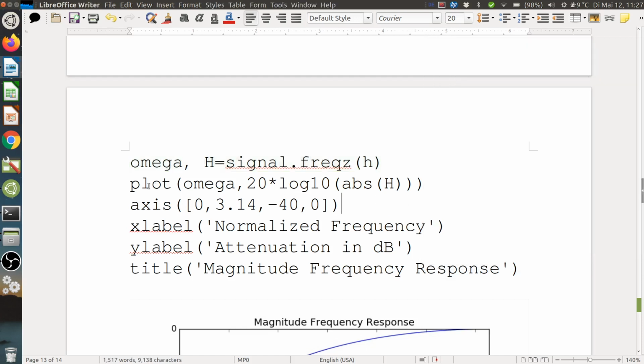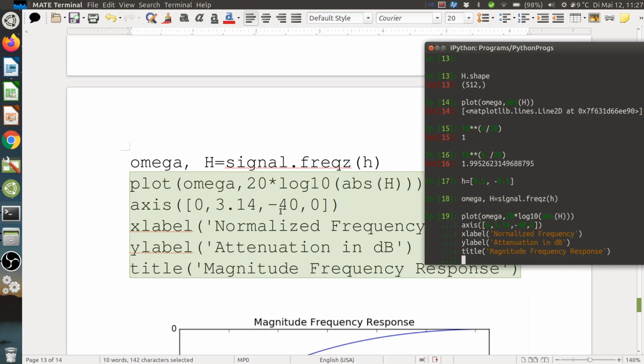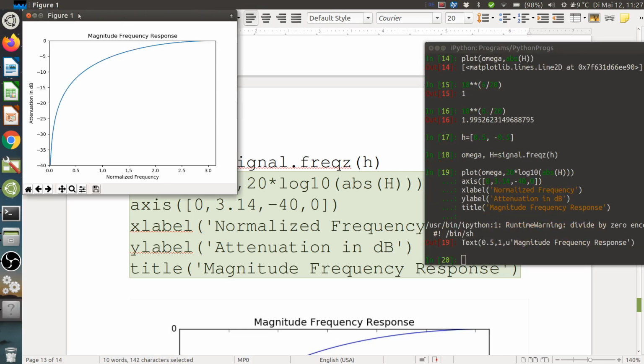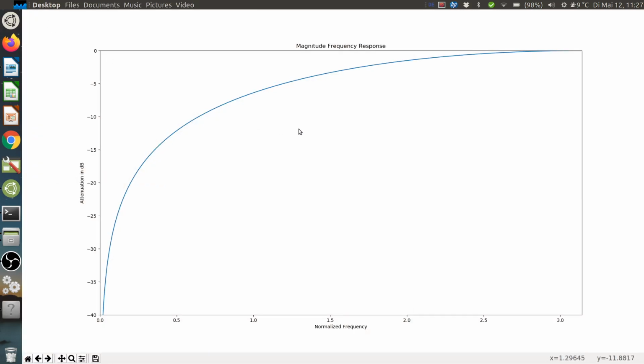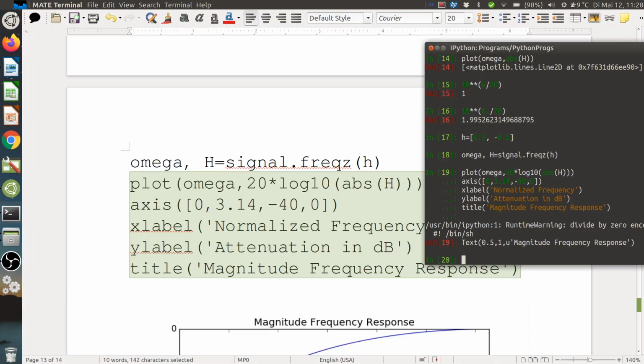Now we can plot it, copy and paste. And this is now the result. And here you can see it almost looks like our running average filter, except that it's flipped between high and low frequencies. It's flipped around. So frequency Nyquist looks like frequency 0 for the low pass filter. So it's like if we would mirror the frequency axis. But the shape is actually exactly the same. So it shows a close relationship between the two filters.